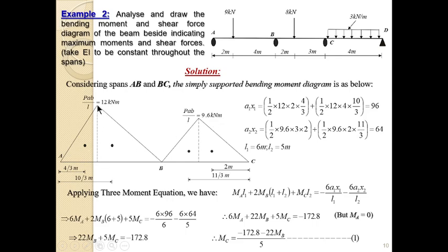Now, since this triangle is not an isosceles triangle, it is not symmetrical. You cannot just put the centroid at the mid-span. So we are going to split it into two right-angle triangles. When we split this, remember the centroid is 1/3 from this side and 2/3 from this side, and the centroidal distance we are looking at is from the external support.